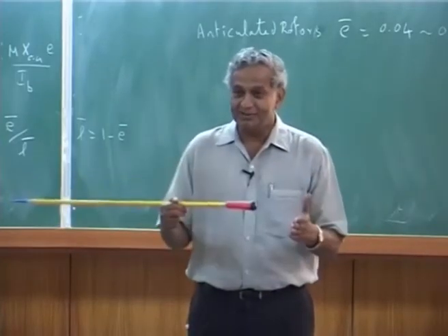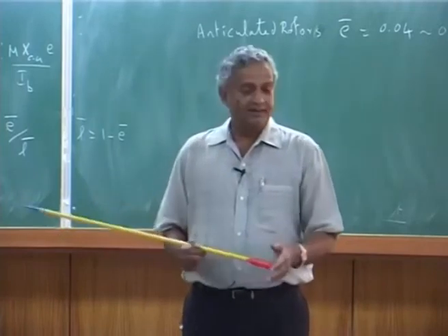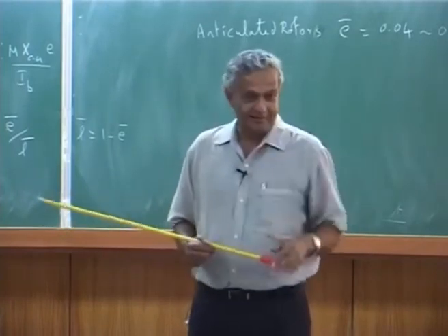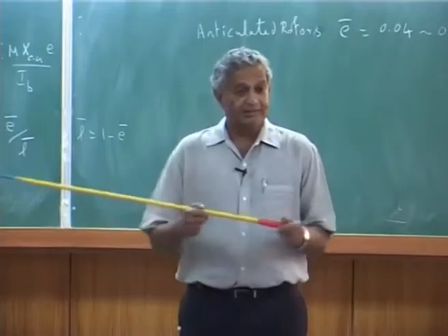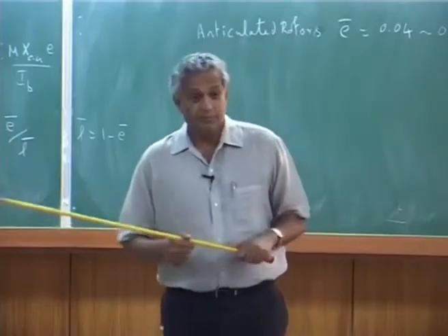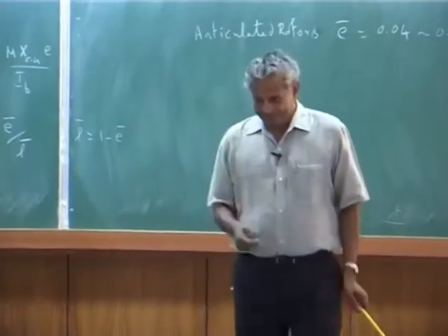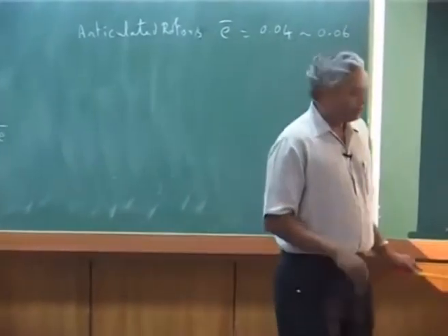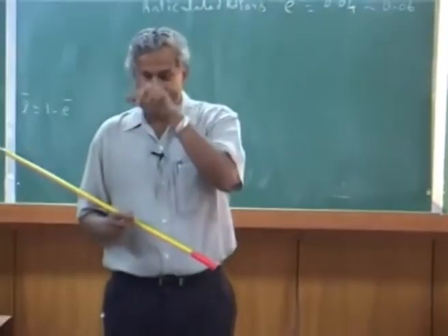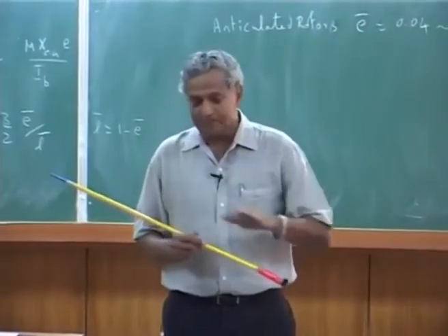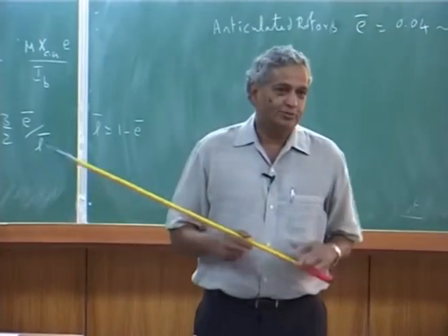That means physically you have to attach it, and they have to check the damping level, oil level, or how good it is. Okay. But for the tail rotor, usually you go to stiff in plane, but then keep the frequency away from the flap lag instability zone, and you do not have to put a damper.